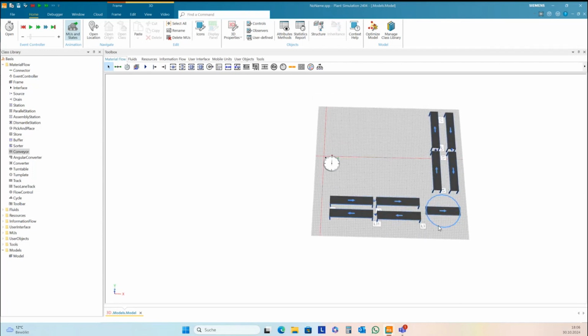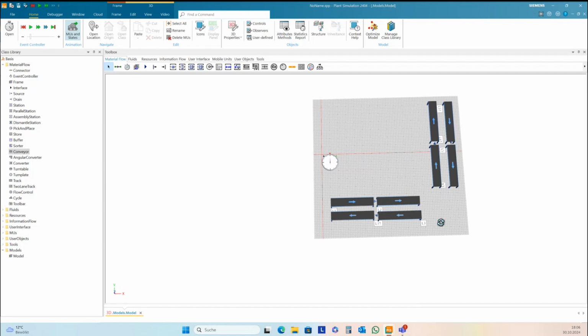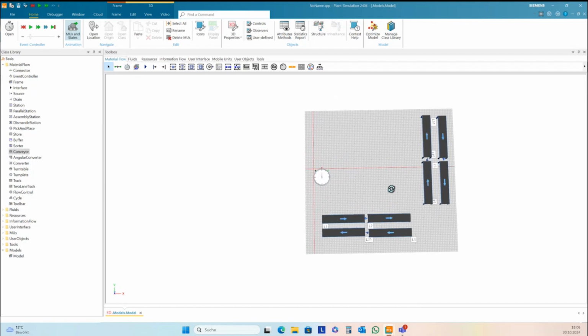And today I want to show you one approach based on track and transporters. This is, for me, the old way, because in 2D, you could make a lot of objects in this way to load a transporter on a transporter and another transporter on a transporter. And this was the default setting, for instance, for the multi-portal crane until version 16.